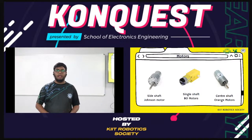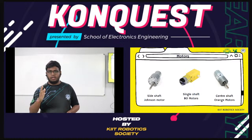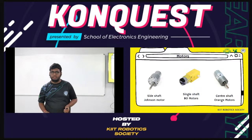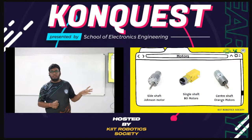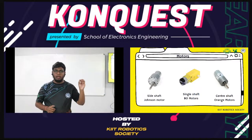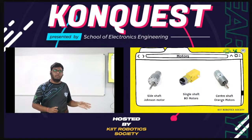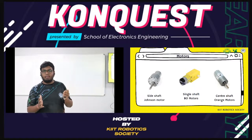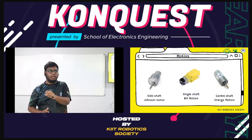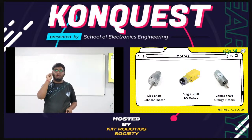The original ones were probably not locally available, and the available ones had high prices. The ones available in the market were said to have an RPM of 300 to 400, but it's not really that; it's about 200, 250, 350, something like that. So you have to keep that in mind while choosing your motors.